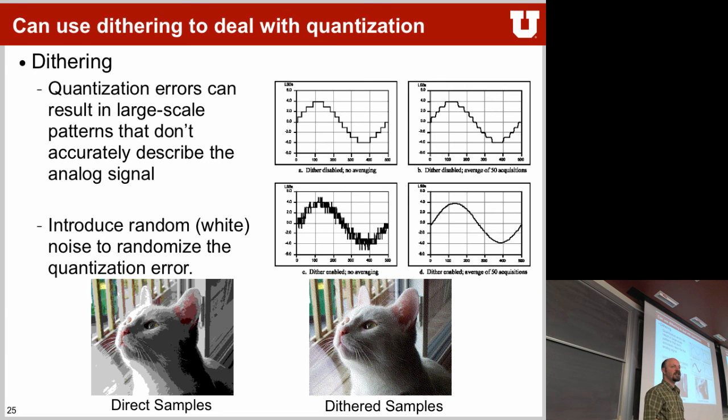Now assume we actually inject white noise that just gets added to the original sine wave. If we add white noise on top of this, and we sample it, and look at each and every sample, we will get something like this. Because of the white noise, sometimes the sample would be higher, sometimes lower. The key here is that the chance of being higher or lower actually depends on where the signal was at. Because it's white noise, if we average it, on average it will be 0.